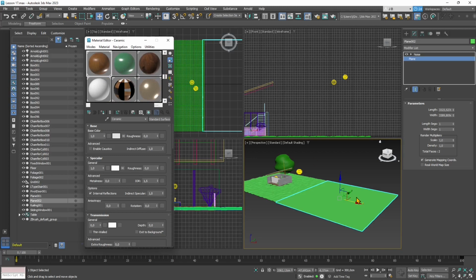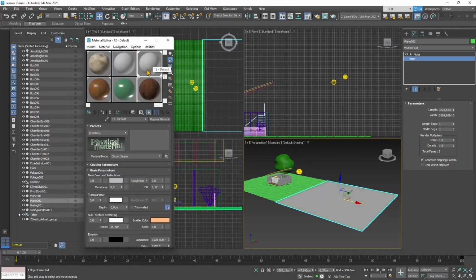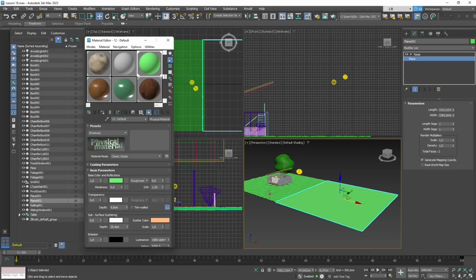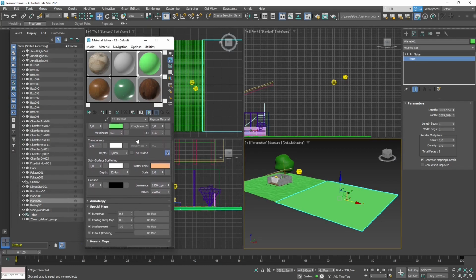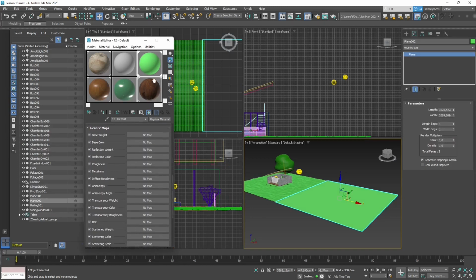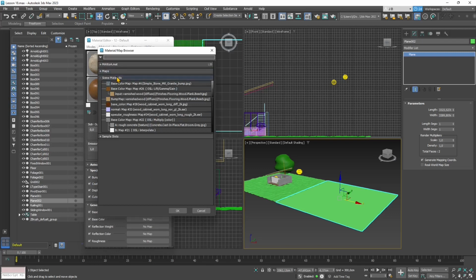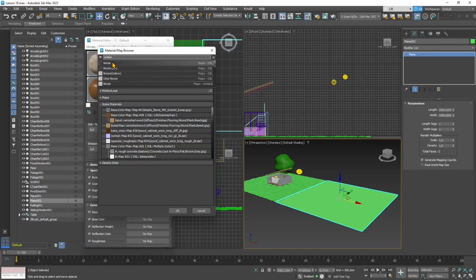So instead of actually creating the waves of the swimming pool, I can create a material and apply a bump. So let's make this again kind of a green material, and we're gonna see the difference between an actual extrusion or an actual displacement and a fake extrusion like a bump or a normal. So we will create later also materials using displacement instead of bump. So right now I just want to apply this to the bump map of the standard physical 3ds Max material. So you can see there is a noise procedural map.